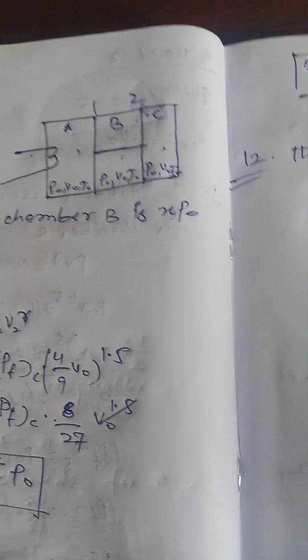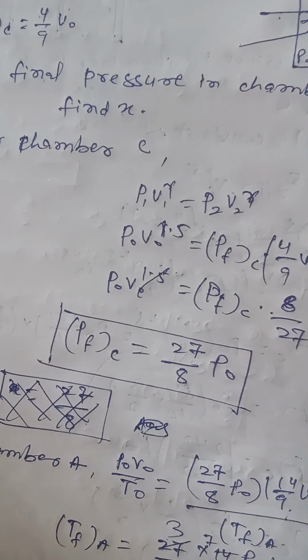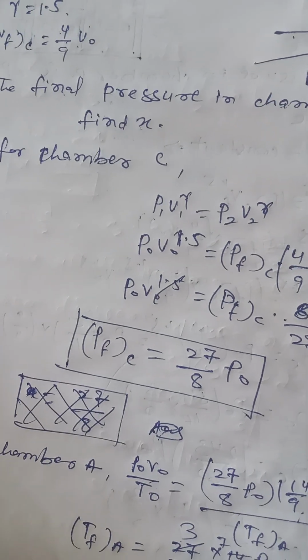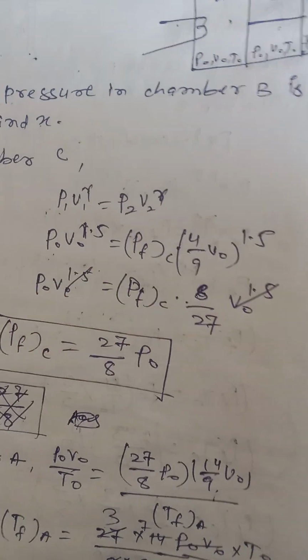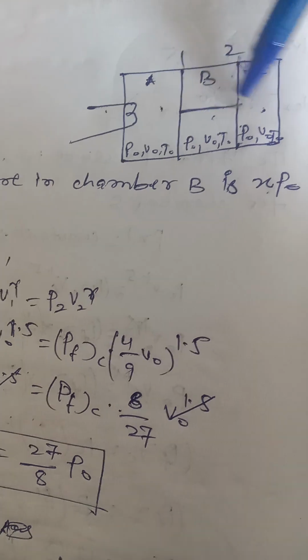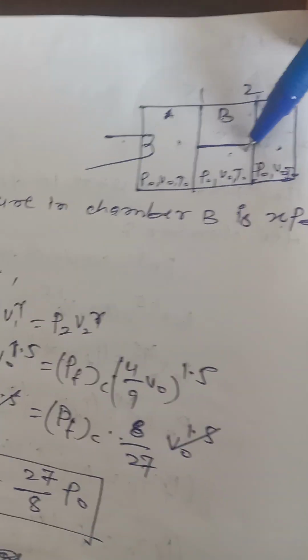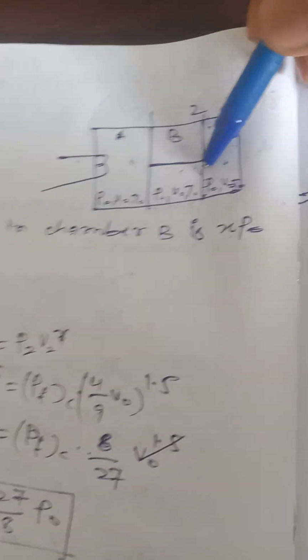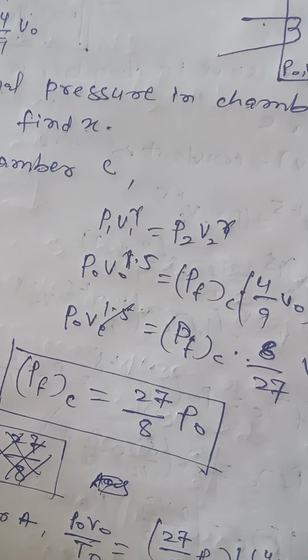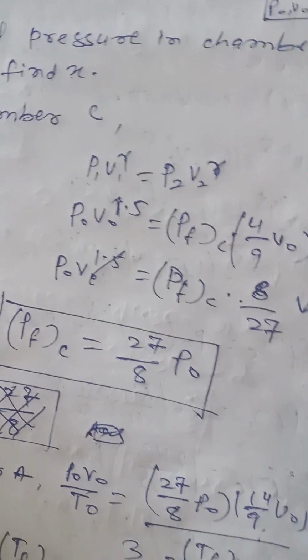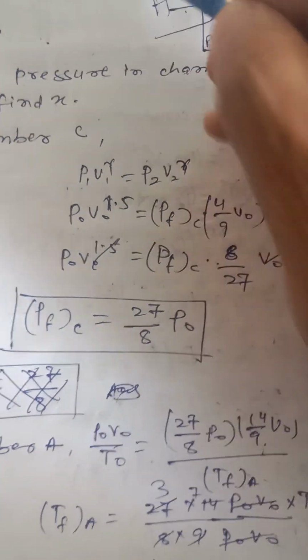Piston 1 and 2 are connected to a rigid massless rod. It means it will not compress the volume. This process will be an isochoric process. Volume will not change for partition B. Heat is slowly supplied by heater H in chamber A,